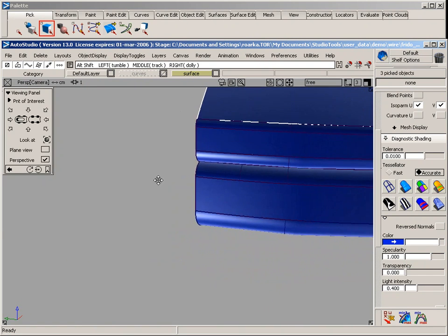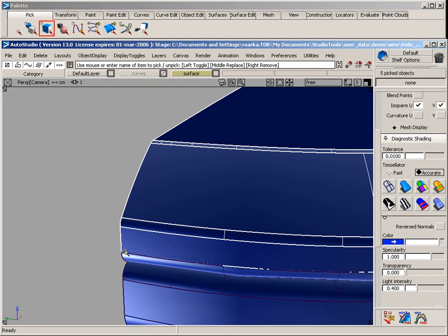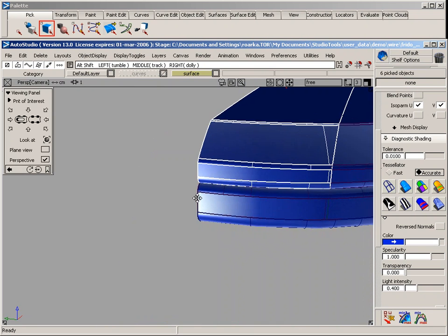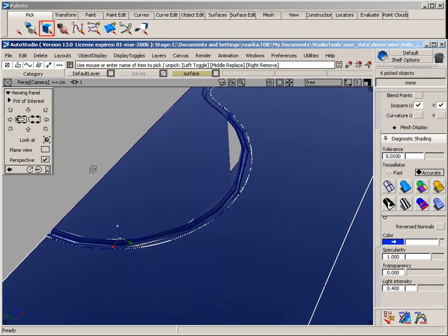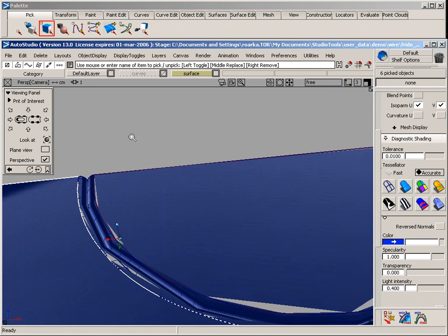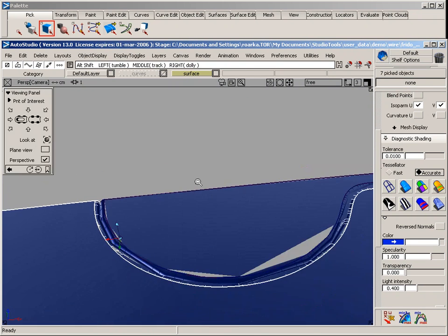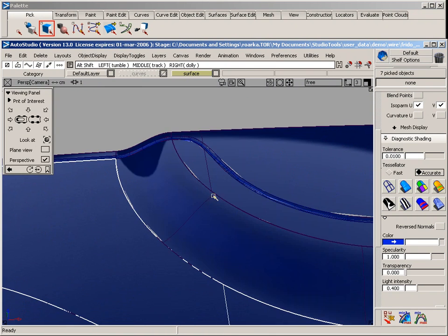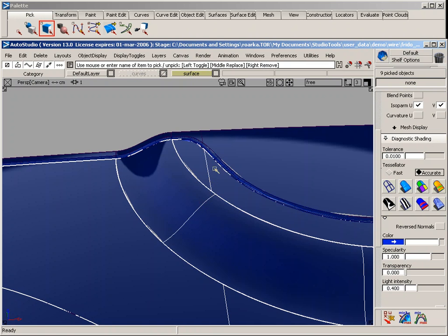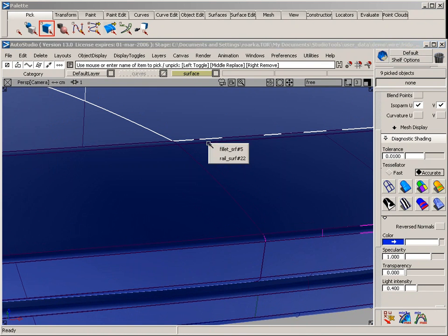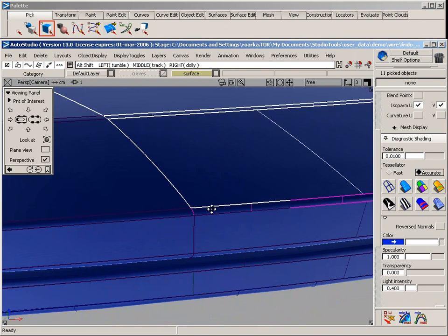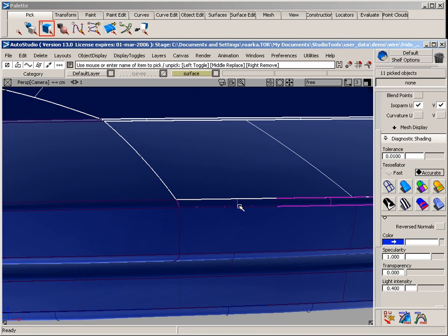This is where I like to zoom in, just to make sure I'm really selecting the right ones. Same for, I'm going to choose half of my part line that I've made, which is this half. Choose these over here. Also make sure that on the other side of this trim divide I can choose the extra components over here.